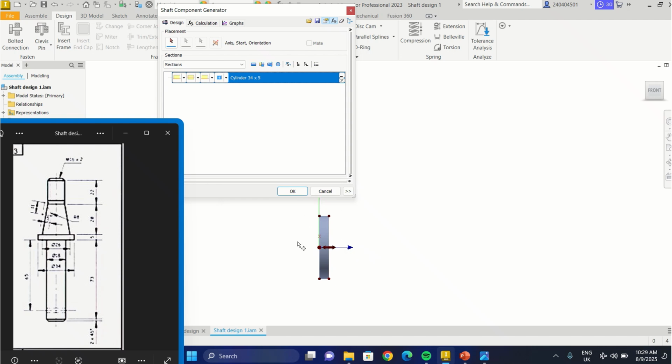All right, so we are designing the shaft. I'm starting from this end of the shaft, right from the bottom. So we have a shaft length of 75, I believe. The dimension is not clear, but let's assume this is 75. A shaft length of 75, and diameter, I guess this looks like 18. This is 34. This is 26. So I'm going to take this as 18. All right, so shaft diameter of 18 and the length of 75.